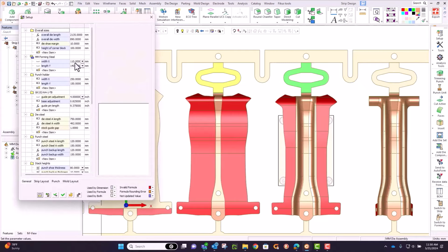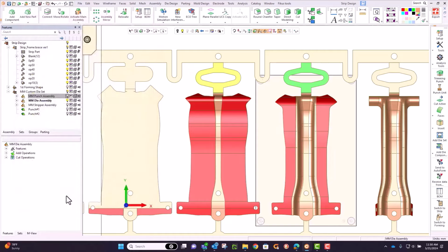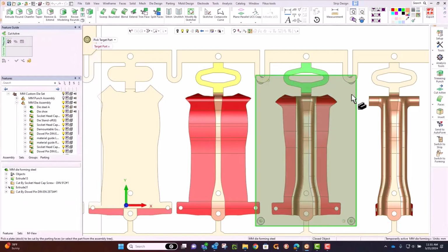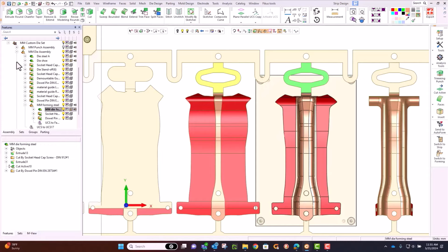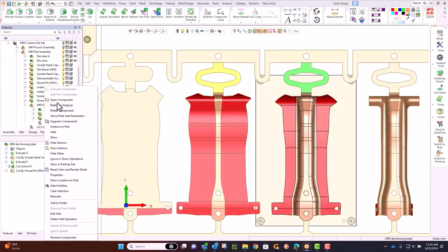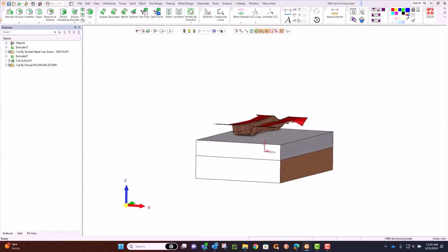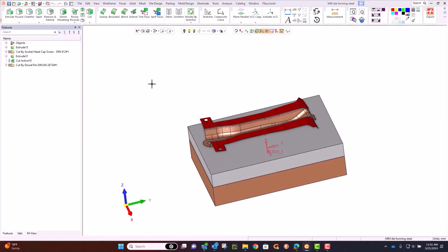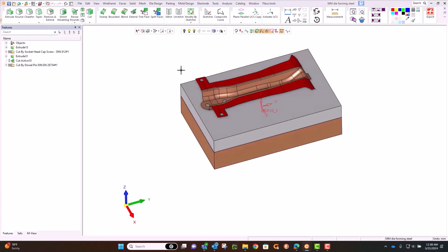I could make it on the fly if I wanted to. I like to work with the library because then I've got all my screws and components with it. So we resized it to fit the overall size. I'm going to now say I want you to work with that particular station or operation. So it brings in that part that had the 2 flanges. Here I did a quick little operation so I can look just at the parts I'm working with. The brown bottom you see is the part of the die steel that sized itself to match what was in the die set, and then the gray, that's going to be the area that I manipulate so that I can capture the geometry of this particular station.